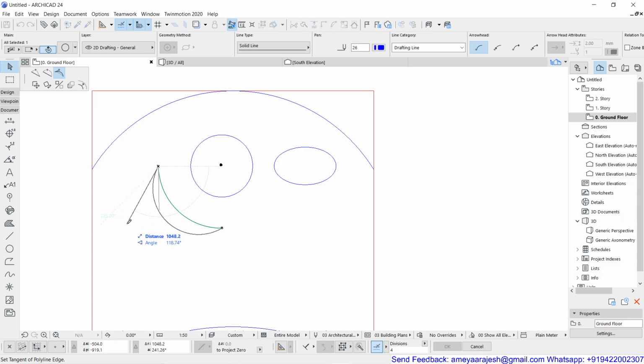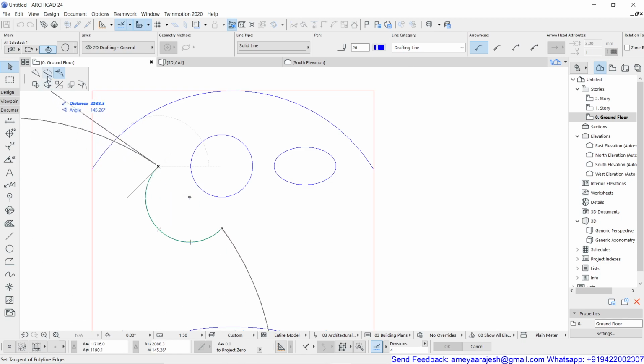So you are defining, or redefining, the arc by showing the new tangential vector. Okay, so this way you can make it as big as possible or as small as possible, but it will always be an arc segment. You cannot convert this by default into a line by using this option. Correct? So let's try to take some value. Okay, and this is my tangential vector that I have redefined for this particular arc. Again, I'm going to click on the same, and this time you can check out, curve edge is nothing but what?